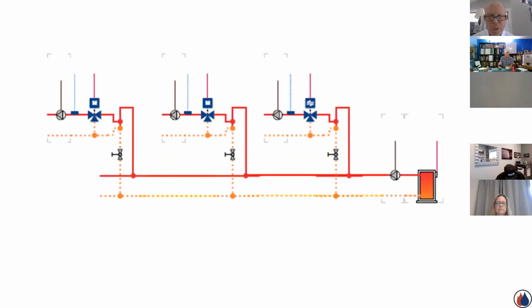So the people would say, well, what should it look like? And this is just a quick example, but what we're doing here is showing, sometimes in the primary-secondary world, what would be referred to as a crossover bridge. And within that crossover bridge, here's my common pipe. It's common to the primary, and it's common to my secondary circuit. I can go that way, I can go up the bypass. But that's a common pipe, and that would solve that pressure differential. This valve would never even see it because this common pipe would handle it and take care of it.